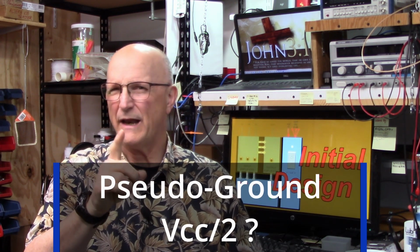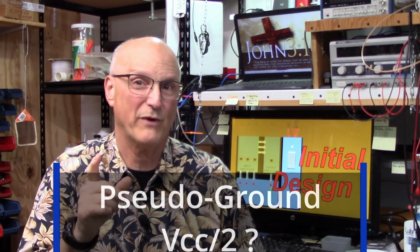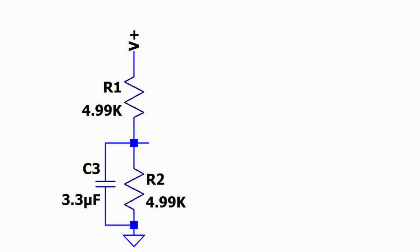But you know, I did say in the previous video that I would show you how to provide that pseudo-ground voltage without using a regulator to do it. And while the need for it no longer exists, I will make good on that promise just now. So here's how we're going to do this to ensure that the voltage actually follows the power supply voltage. We start with a resistive voltage divider whose output is heavily filtered with a capacitor. This voltage must be nice and clean and stable.